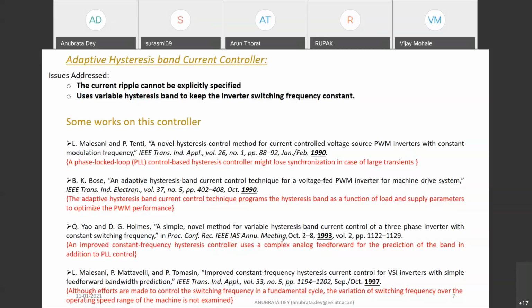In any control, if you use a feed forward term, that may lead to some noise or some control issues, because if you don't put the right amount of feed forward term into the control feedback loop, it might work in a very bad manner. If it is all right, that is fine, but if it is a little different, it may become worse. So that is another problem.